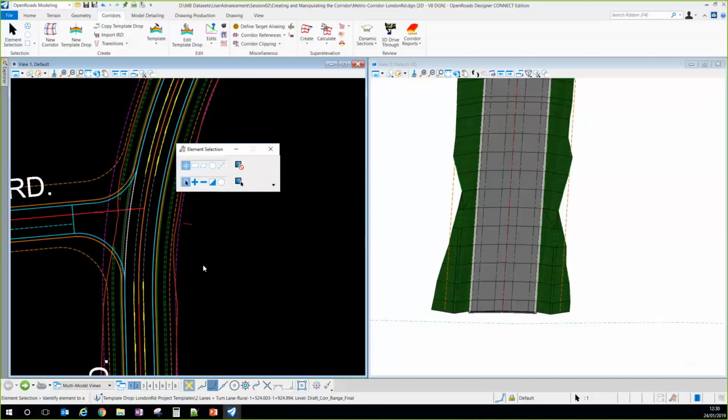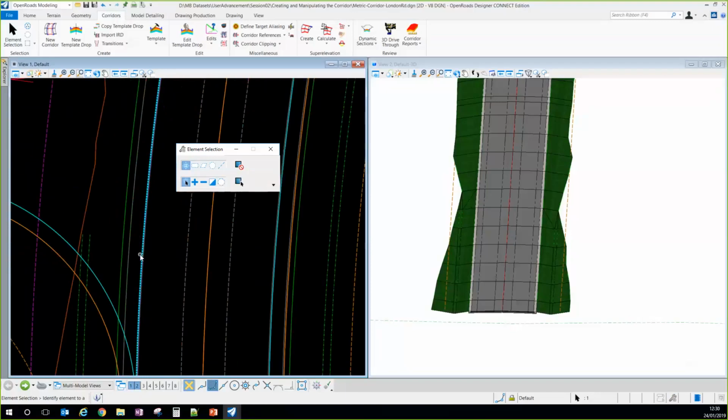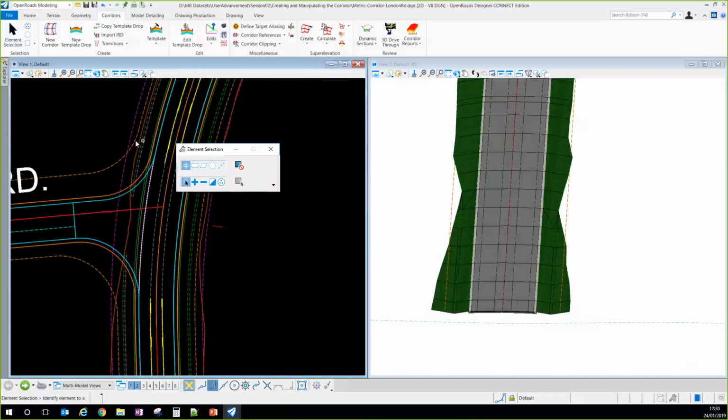So what is a display rule? It allows us to display or not some components depending on some conditions. And we can define that when a specific element is encountered, those elements are not displayed. For instance, what does it mean? It means we can say to our template that every time we find this linear feature with the feature definition match line, so we can see it here, this one, don't display these components in this part.